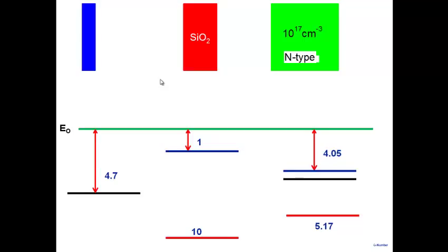And an insulator, no matter how insulating it is, will allow a little bit of current to flow. It will allow charge to flow. There's nothing like infinite resistivity. So if you leave it for long enough time, the charge from here will leak through SiO2 and come to the metal. So even in that case, you will reach equilibrium.